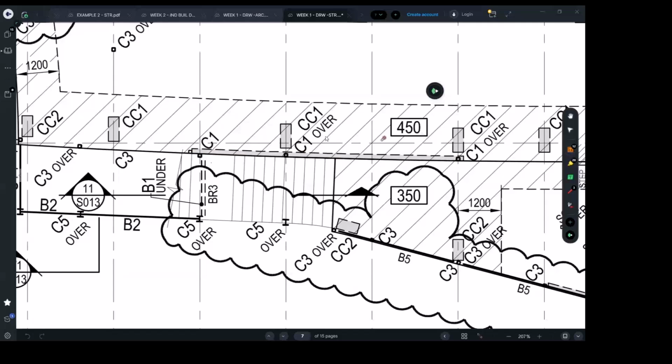So people go and build the concrete columns, right? And they say, no, let me delay, because maybe his friend, the block contractors, are busy. So they say, don't come now, come next month. But hang on, you have to build the block wall before, because you have to physically connect it together, right? So you can't just say, I'm going to build it after.